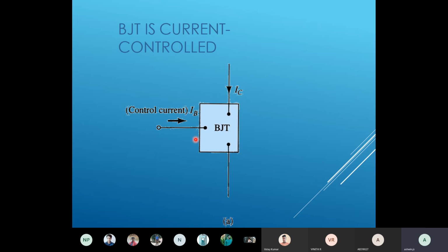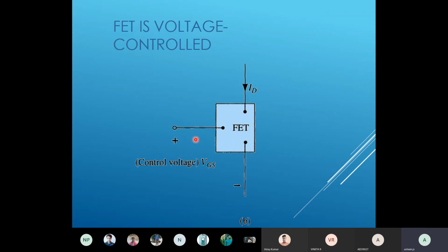And if you see the FET, the field effect transistor, the FET is a voltage control device. Here we have three terminals. This is the drain, this is your gate, and finally this is your source. Okay, so keep remembering the pin names. The FET is a three terminal device, and one of the terminals is the drain, and the second one is the gate. The gate is common in the SCR also. We found a gate in the SCR as well as the triac. We have seen the gate, you know the purpose of the gate terminal, and the other terminal is the source.